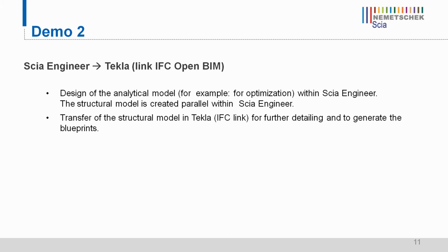So we will make an analytical model within Scia Engineer, and this analytical model in Scia Engineer will also contain a structural model. This is always like that in Scia Engineer. And you can create an EFC file from the structural model which can be imported in Tekla, but actually it can be imported in all kinds of different programs. And we will transfer the structural model in Tekla for further detailing and, for example, to generate blueprints.